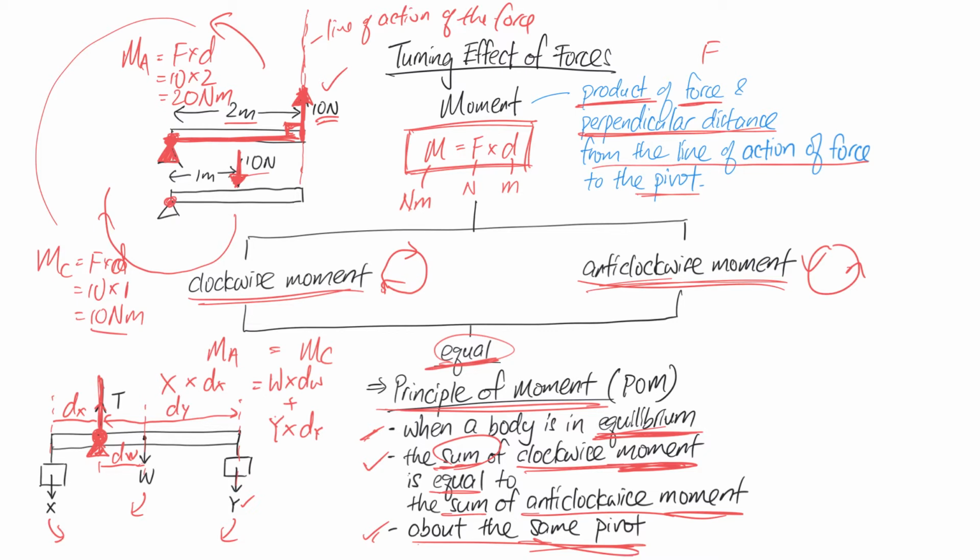One last important concept is, if you look at this system here, it's balanced, it's in equilibrium. In other words, it's like it's suspended in the air because of this string holding onto it, or the support. This pivot is supporting the whole rod. Now there are two conditions when something is in equilibrium, and almost all students will know that when it is in equilibrium, the principle of moment will be applied here. This condition is met where the anti-clockwise moment equals the clockwise moment.